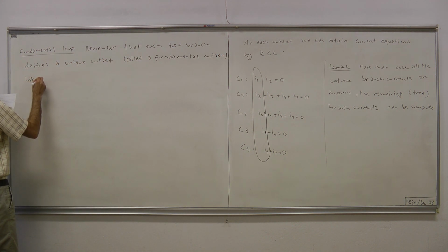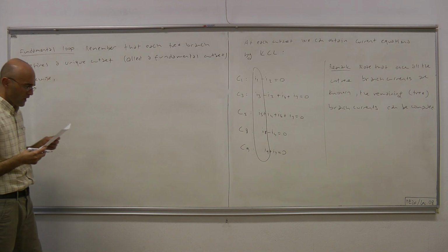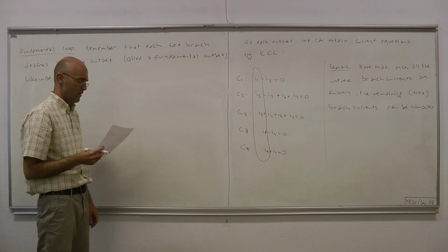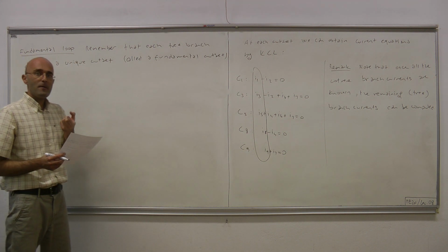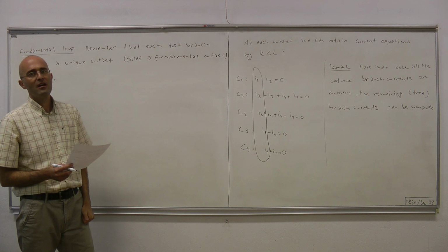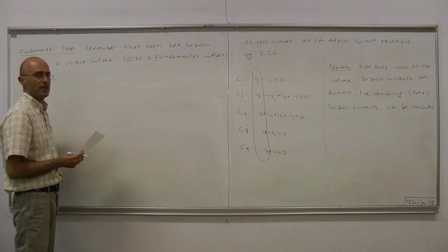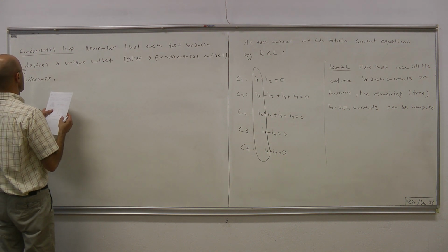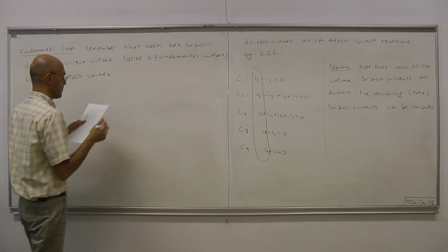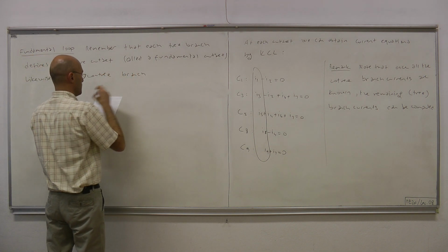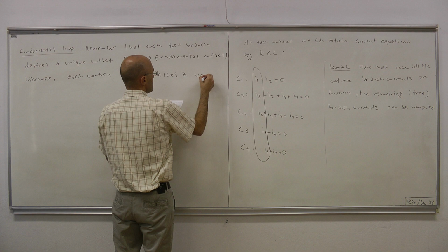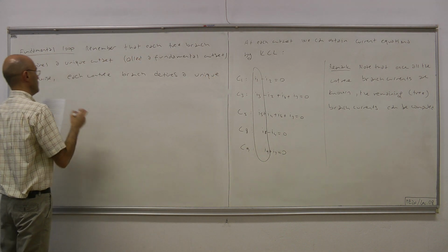Likewise, each cotree branch defines a fundamental loop, a fundamental closed path, in the sense that that loop is constructed from that particular cotree branch, and all the remaining branches are coming from the tree branches. Likewise, each cotree or non-tree branch defines a unique loop.